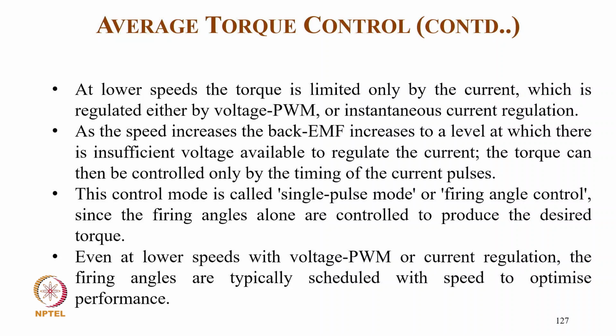It is regulated either by voltage PWM or instantaneous current regulation. As the speed increases, the back EMF increases to a level at which there is insufficient voltage available to regulate the current, and the torque can then be controlled only by the timing of the current pulses. So this control is called single pulse mode or angle control mode, since the firing angle alone is controlled to